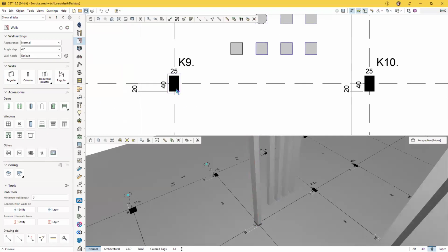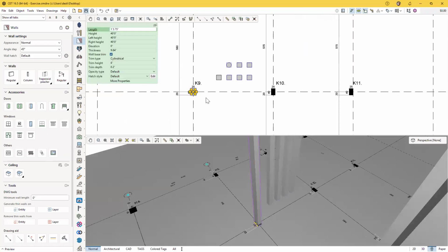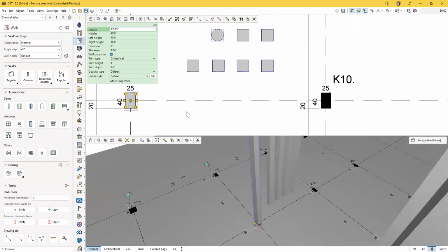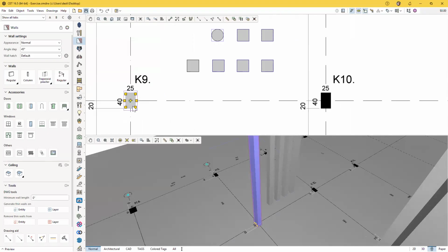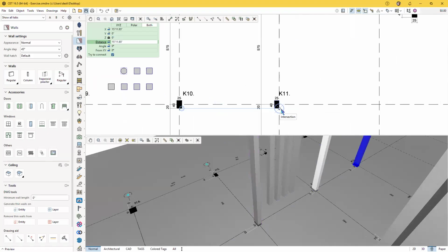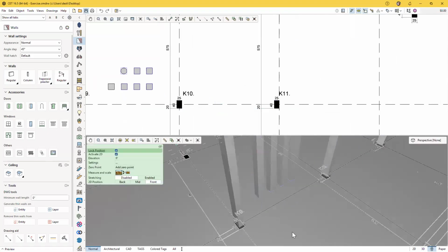So if you've got things that are kind of a funny shape, you can use this tool. And again, you could do a copy or a copy with a base point. So if I do a Control-Shift-C, I can then copy this wall and then choose that base point and just create all of the copies that I need that are the appropriate size already.